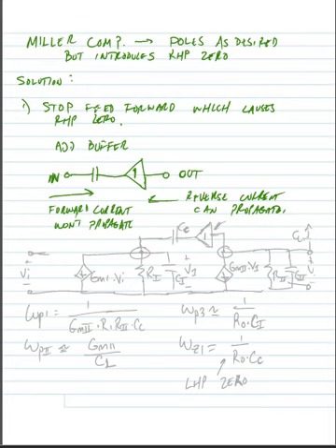Okay, so looking at our simple circuit model for our op-amp, we got our input coming in here. We had a voltage dependent current source, big GM1 times Vn. We have the output resistance of the first stage, R1, and of course some capacitance from that first stage, C1.